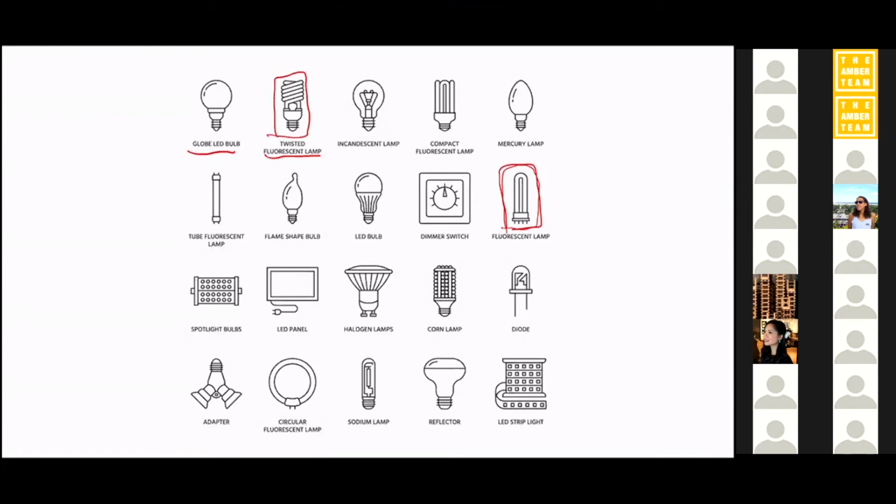So if we know we're going to have compact fluorescence in our fixtures anyway, instead of taking an Edison screw and screwing it in and then converting it with the throwaway equipment, we would rather buy cheaper versions of this and just put one ballast inside the fixture. So it's actually inside the equipment that's permanently part of the building.